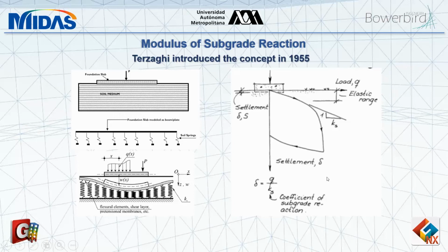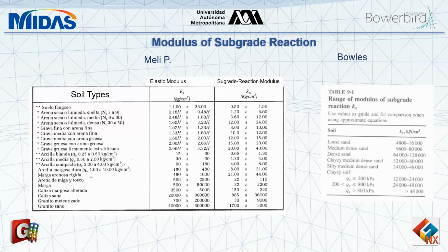So from these kinds of curves, loading conditions, we can get the coefficient of subgrade reaction, the K value, and that would be essentially what's inputted as the stiffness for the spring. And there are suggested values for this. This is not a new concept, and so one can Google, or there are plenty of texts available for structural engineers if they don't have access to lab reports or to a geotech team or company to help them. They can basically find these modulus of subgrade reaction values for different kinds of soils from tables.